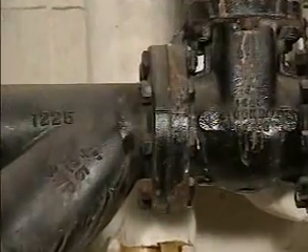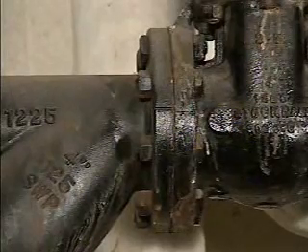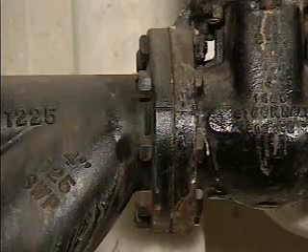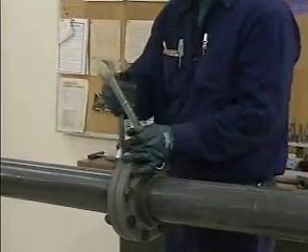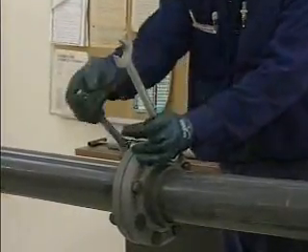A flange is a flat metal plate attached to the end of a pipe. It can be bolted to a flange on the end of another pipe to form a flanged joint. Flange joints are leak-proof joints that are easily taken apart for inspection or maintenance. The many individual pipes in a piping system can be connected to each other using various types of joints. The devices used to make these connections are called pipe fittings. In this part, we'll look at some common fittings and examine their functions.